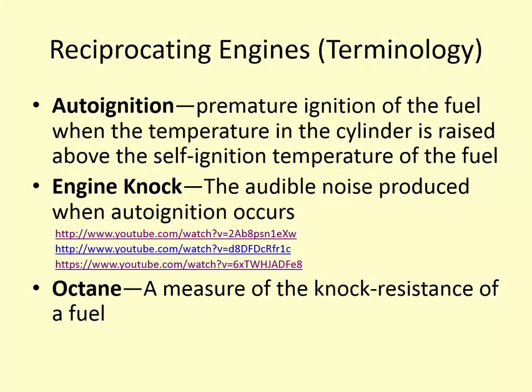Okay. So what's happening there is the spark plugs are firing after the fuel has already ignited, and the timing is all off because the cylinder is being pushed and compressed prior to when it was supposed to. And so it causes really a lot of problems in the engine. You have a significant reduction in your power output, and it's just really not a good thing because you have incomplete combustion and it causes problems with your cylinders. It can cause fouling and things like that.